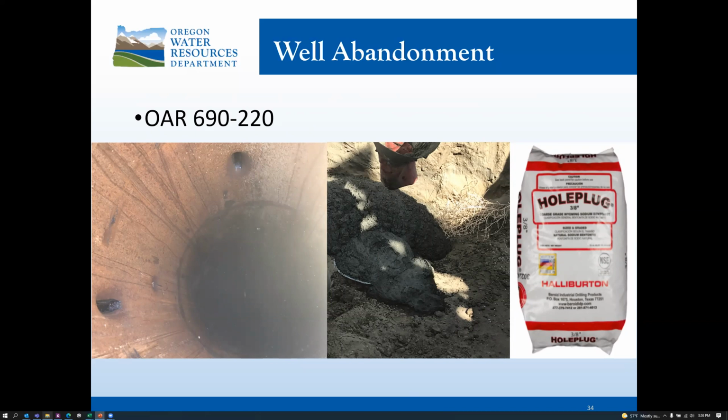The annular space between the casing or liner and the drill hole wall shall be effectively and completely filled with cement grout applied under pressure. Perforations are not required in the sealed interval, provided proof of the original seal can be verified with the original well report. The verified seal interval shall be filled with cement grout, concrete, or unhydrated bentonite. Uncased portions of a cased well shall be abandoned and filled in accordance with these rules.